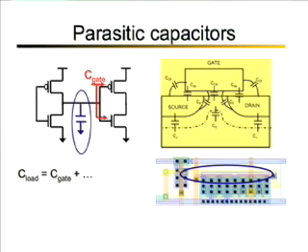On the right hand side, I am showing a typical schematic of a MOSFET with all the different parasitic capacitors, and these parasitic capacitors, if I may point out, are all dependent on the width of the device. So this part can be looked at as the device parasitic capacitor, and they are width dependent, meaning that all these parasitic capacitors will scale as a function of W, or width of the device. Apart from that, we have another capacitor which does not scale with the width of the device. This capacitor is essentially the capacitor of the interconnect when one wants to join one cell with another.